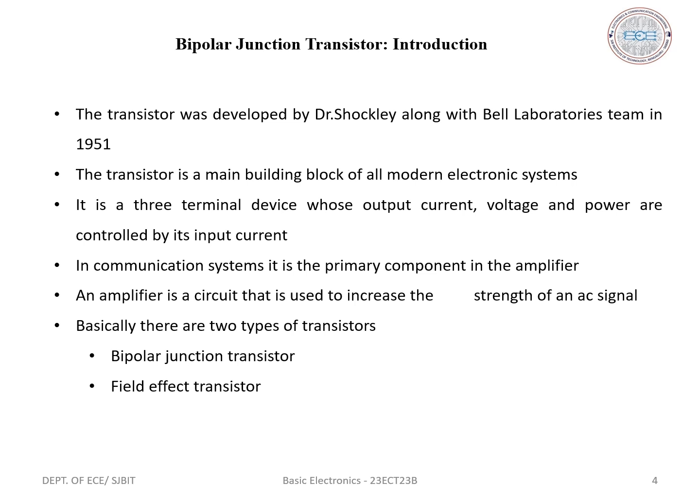A transistor is a three-terminal device. The terminals are collector, base and emitter, out of which the base is the control terminal. That is, if a signal of small amplitude is applied at the base, then at the collector we get a signal of larger amplitude in magnified form. This is called amplification. That is, transistors can be used for current amplification.